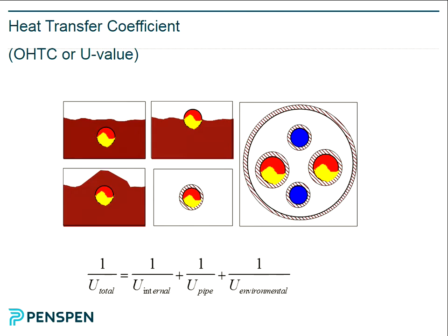Asphalt may be a reasonable insulator, but it's not very practical to apply in thick coatings. Polyurethane foam is an extremely good insulator, but has no mechanical strength. Sand and mud are actually pretty good as insulators. So you can add all these to this equation for the different layers to calculate your contribution to your overall heat transfer coefficient from the pipe.